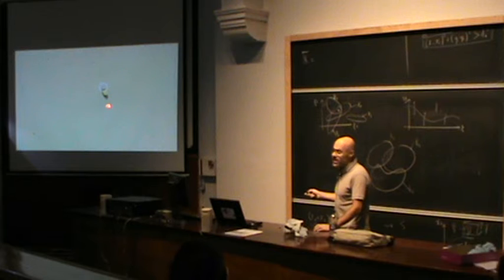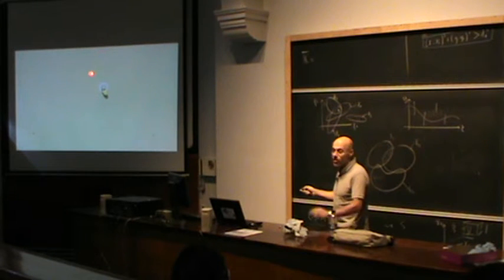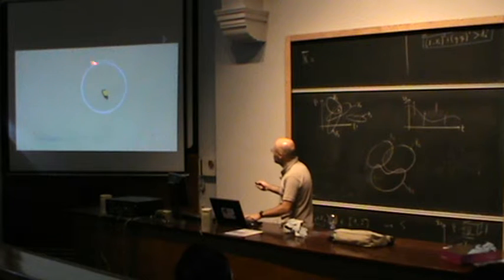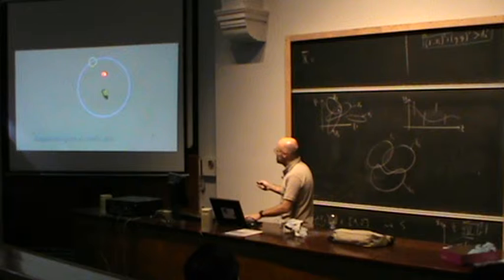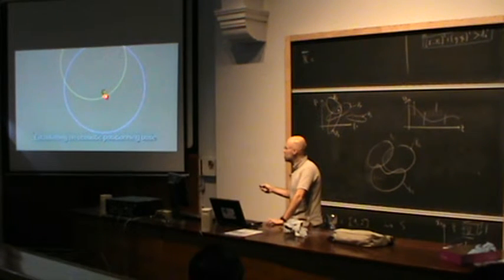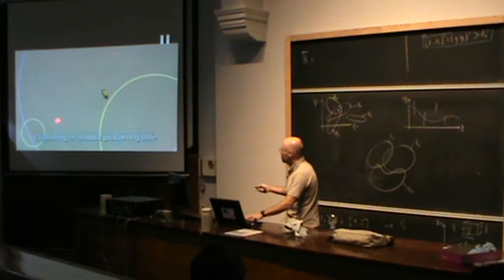It's a range-only approach. It means that it will send an omnidirectional wave, and this one has a small program and it will answer. So I will show you now. The wave, here, as soon as it has received it, it answers. The robot here measures the time of flight between go and return. This is done for all transponders.